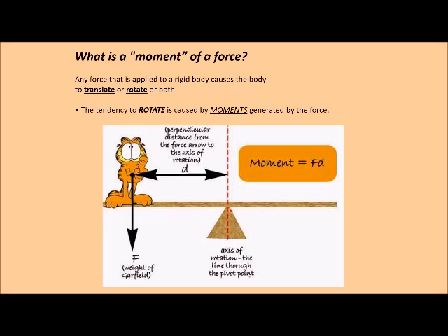So you're going to want to really pay attention to what the system is trying to rotate around. And when you figure out what it's rotating around, that's how you're going to define this distance, this lever arm, between what it's rotating around and where the force is applied.